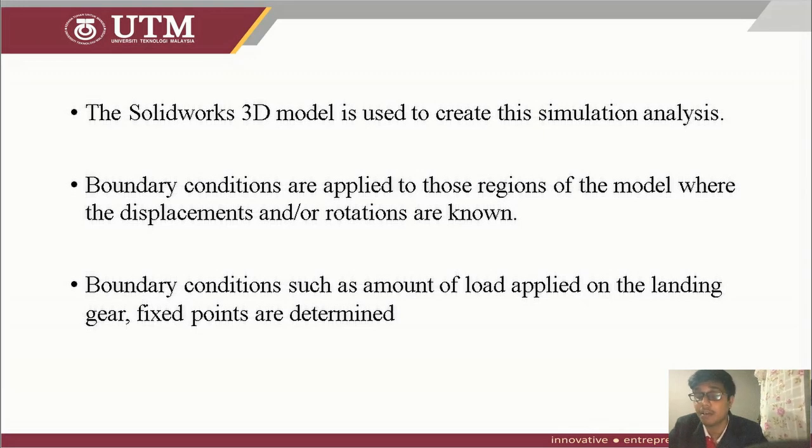For the main landing gear, the top, where we connect the fuselage and the landing gear, will be used as the load point, and the fixed point will be at the tire.